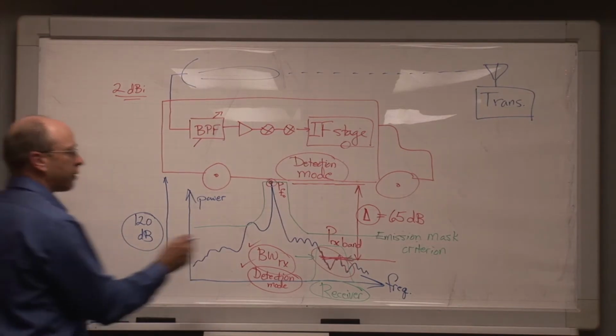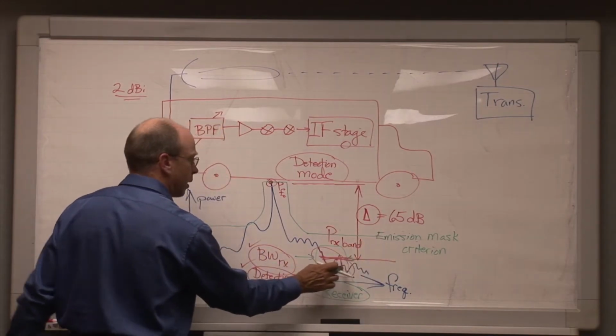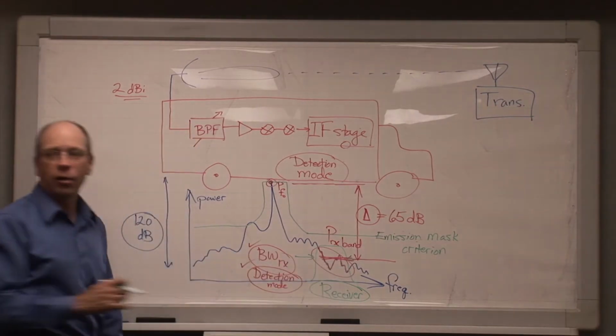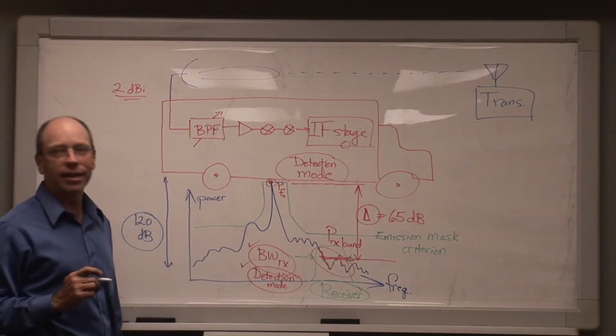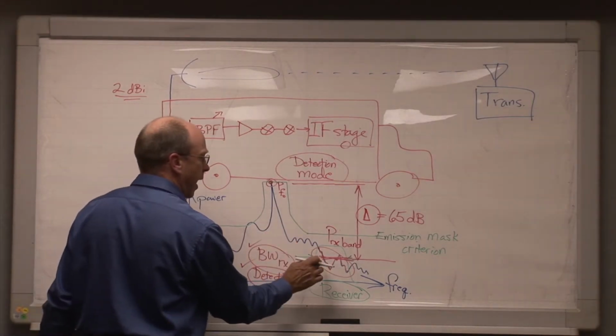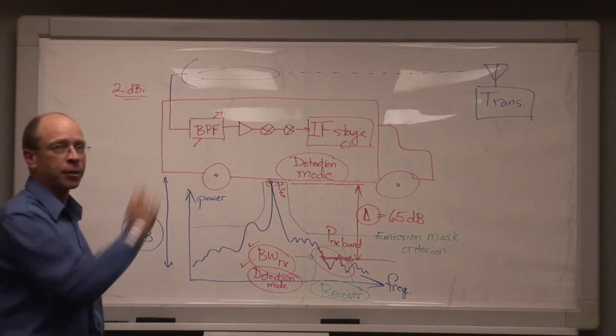So we'll note whether it does or does not meet the emission mask criterion, because if these emissions are directly causing the receiver's problem, this could bear importantly on the question of who's going to, in effect, pay to get this fixed. If this thing meets the emission mask criterion and it's producing interference, then the people who have the receiver may have to pay to put a filter on the transmitter to get the problem fixed.